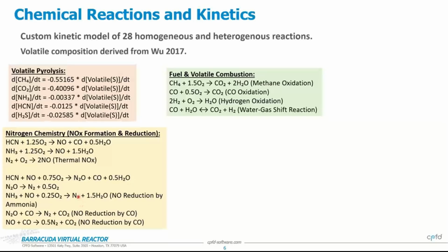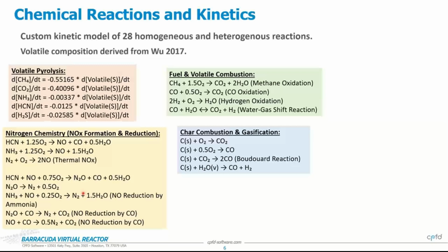And then recover nitrogen out of that, which is what you ideally want to be leaving your riser section. Then there is a set of reactions taking place in the discrete phase, or your particle phase. Once the gases leave the fuel material, you're left with primarily char, and char gasification and combustion reactions also take place. The brackets for the S represent that this is a solid material. That's the representation here, right?